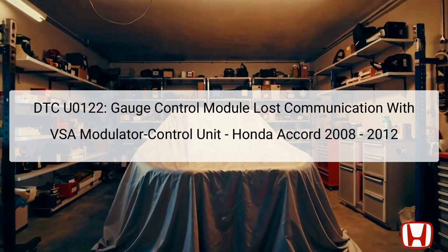This error code suggests that the required messages for the VSA system are not being transmitted or received correctly, which impacts the vehicle's performance regarding stability control. Regularly monitoring the VSA system is essential, as malfunctioning components can lead to a loss of critical safety features in the vehicle. Technicians often leverage the Honda Diagnostic System, HDS, for effective troubleshooting.